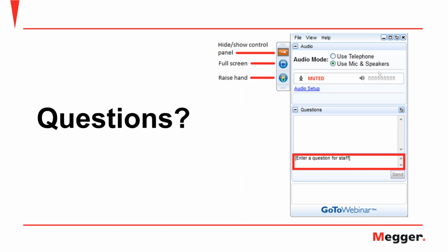Somewhere on that line, there is probably a point where the resistance of your test ground stops, and that's what you're looking for, but you can't see it because they overlap. And so the slope method puts in a mathematical crunch that looks for where that point is. And we will cover that fully when we go into the methods webinar in a week or two. Next.